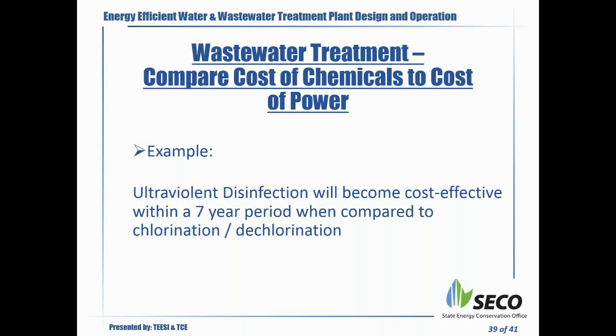And so we've been recommending that you replace your bubble disinfection with a mechanical type mixer or a submersible pump that would mix it underwater with no bubbles, so that chlorine will not be stripped from your wastewater, and you'll get the full benefit of your chemical.